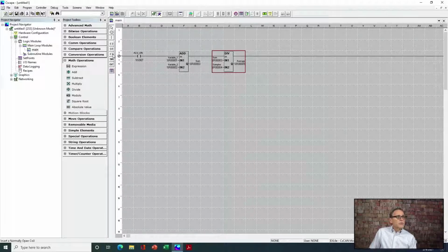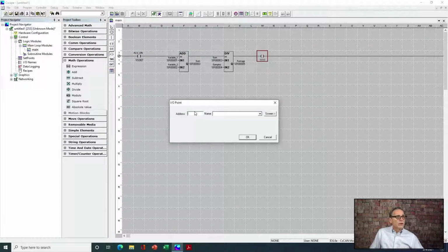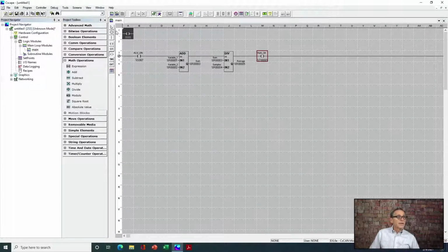So one option you do always have to try and flag an issue with a function block is, with a math block for instance, you can put a coil at the end of the rung that says Math. Then if you ever have a problem with one of your math blocks, where they have an overflow or an issue with a divide by 0, in that scenario this has been flagged because this bit will be off. So this is just basic cascaded math functions, simple arithmetic stuff.